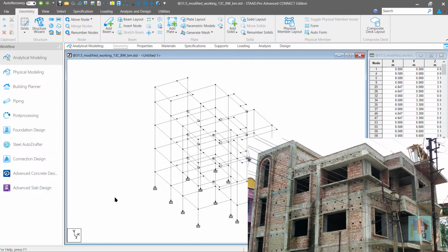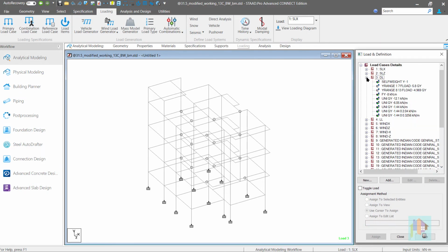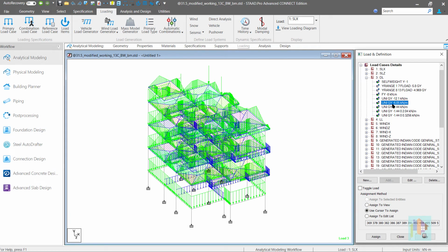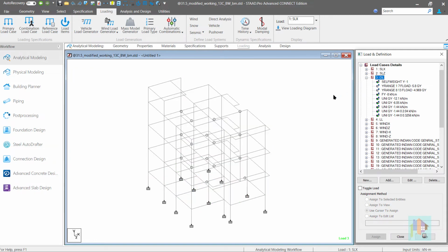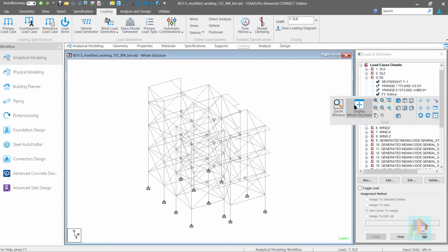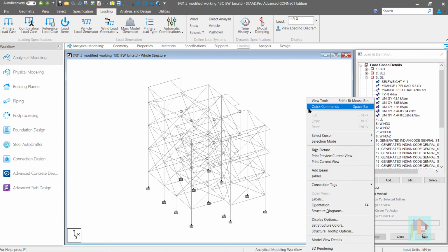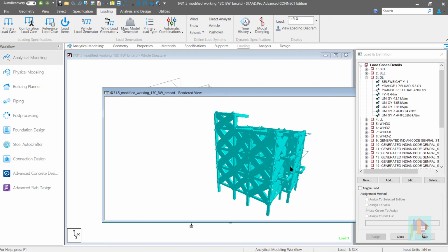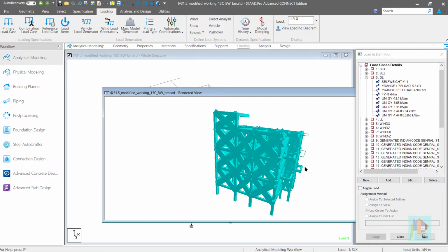When you design any concrete building with infill brick wall, most of the time we neglect the effect of the wall and assume this as a non-structural element. Load from the wall is applied as a dead load, but stiffness is ignored. It is a conservative approach. Any thick masonry wall with adequate strong material like brick provides enough lateral stiffness and contributes significantly to resist lateral force. If we model these walls properly and consider the stiffness during analysis, it can reduce the lateral deflection and overall reinforcement percentage in the structure.